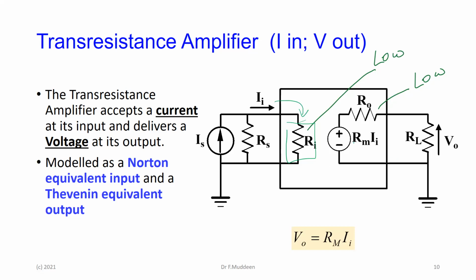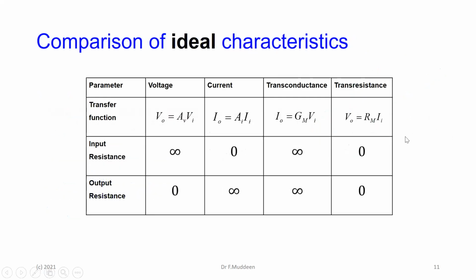And then the amplifier is producing voltage coming out, so what you want is that the output impedance here has to be low, so the voltage drops across the load. Right? And the characteristic of that is something called the transresistance, for which they normally use the symbol capital R. Okay? So those are the four amplifiers, and they're summarized inside of this table here.